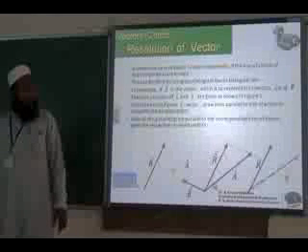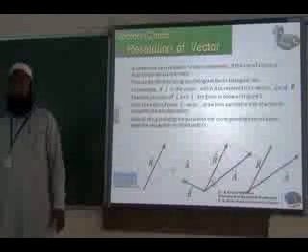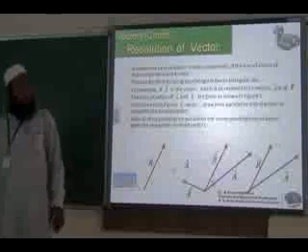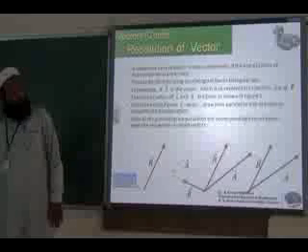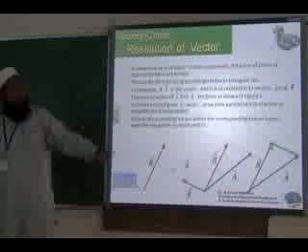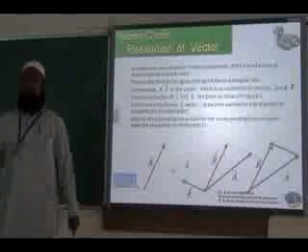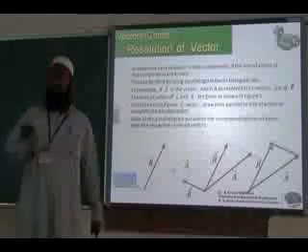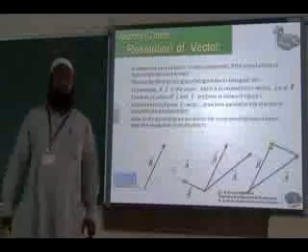Similarly, we can get it using triangle law also, if you know the line of action. From the resultant vector, we draw lines parallel to A from the tail of vector R, then parallel to B from the head of vector R, and you get the triangle. Now the vectors can be found in order. The direction and sense will be obtained in order.